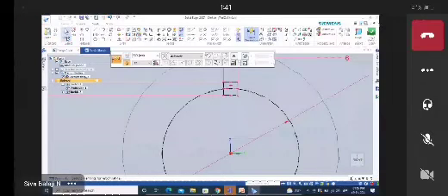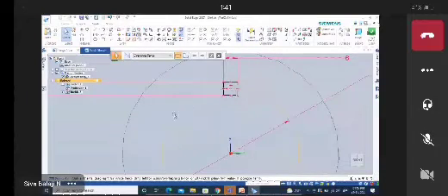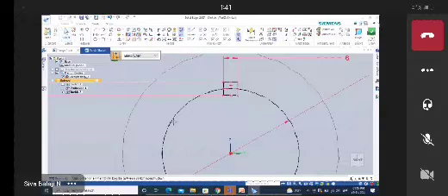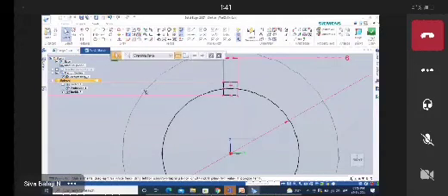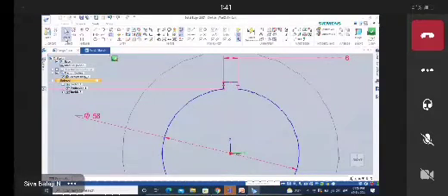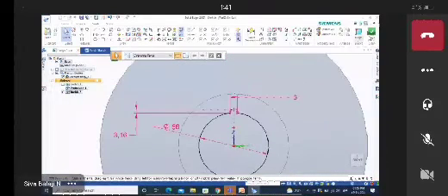But don't convert the circle into reference circle. If you convert the circle, you cannot cut with this circle. Okay, sorry for this step. Now it is the solid circle only. Now you can select the trim command and trim the unwanted entities. Now the constraint will be lost. You can apply alignment here by using horizontal and vertical command. If you apply alignment, it will get constraint.